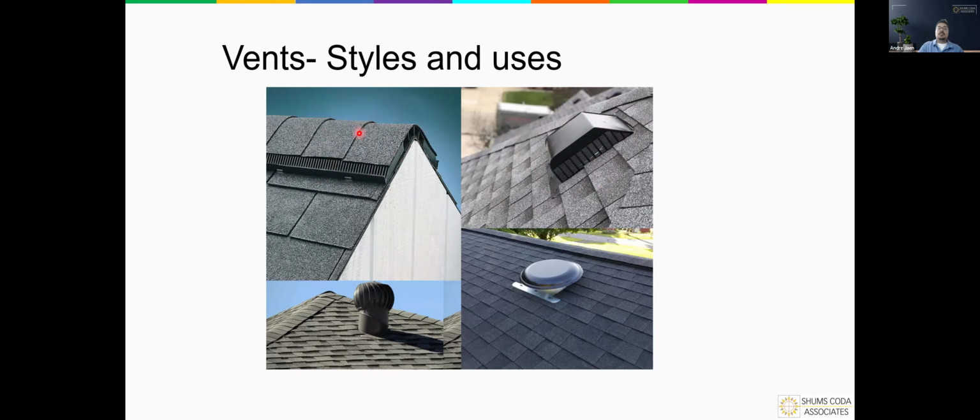And some of the concerns that occur with this are definitely wind resistance and uplift. You get a lot of roofers that shoot this in with their same roofing nails, and they really should, according to the manufacturer, be using 2.5 or 3 inch hand-driven nails to make sure they don't crack through the plastic assembly, and simultaneously that they're getting the penetration into the roof deck that they need, because a 1.25 inch or 1.5 inch roofing nail going through this 1.5 inch deep assembly means that there's almost no bite into the OSB below. And so, some of these things we have to keep in mind.